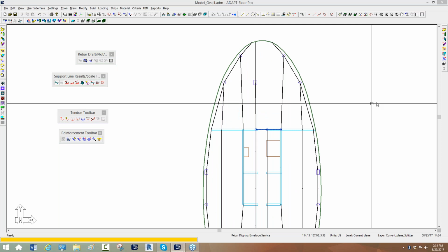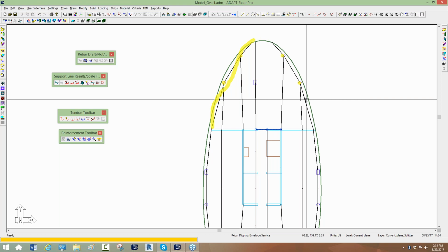Then we have a little bit more of a fuzzy location, which is not apparent just looking at this, but this line, this point, and this point, and then the 4 on the opposite end, these terminate at this support line, which is kind of going around the edge of the slab. And so we have to be able here also to generate tributaries, and because this stops on the inside of the perimeter, we also have to add splitters.